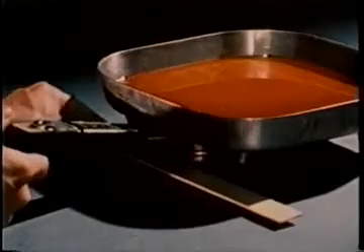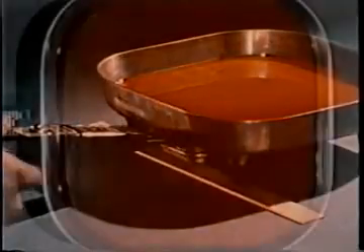On the left, the layer is shallow, the Rayleigh number is below critical, the fluid is stable. In the middle, the Rayleigh number exceeds critical and the Bénard cells are apparent. Going further to the right, we see the size of the Bénard cells increase. Their size is proportional to fluid depth. You can see similar processes in the kitchen and also in nature, where clouds may be the visible trace of cellular convection patterns.